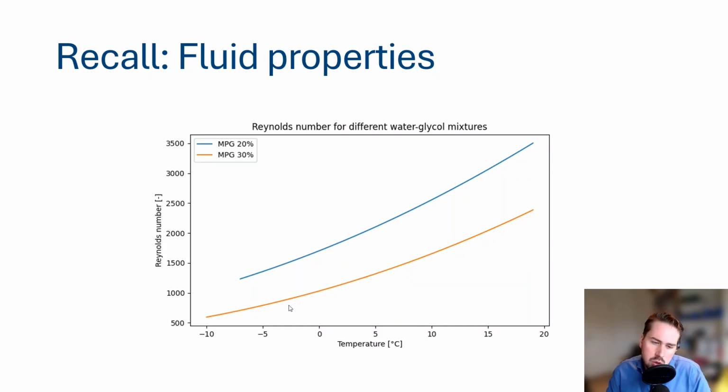And when you go below the freezing temperature, your antifreeze actually starts to work against the freezing of the water, and your Reynolds number drops significantly after that. And it also depends on the level of antifreeze you have. Typically monopropylene glycol is rather viscous, so it has a lower Reynolds number.